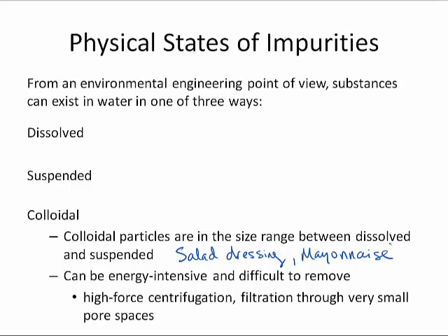The options available to us are high force centrifugation. And when you see high force, you should think energy intensive. This is not applicable for a million gallons per day because of the energy cost. We may also filter through very small pore spaces. This is also energy intensive due to the head loss that must be overcome.